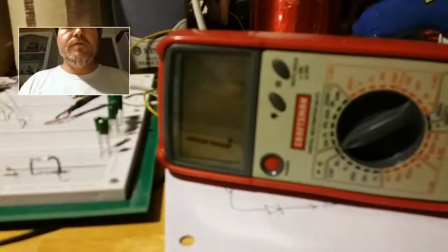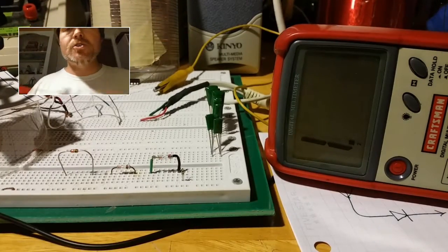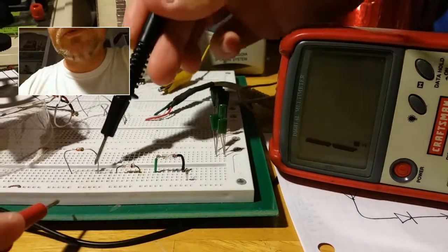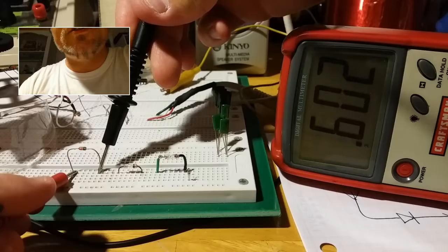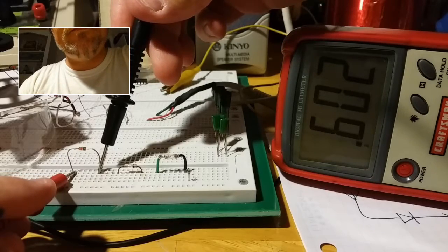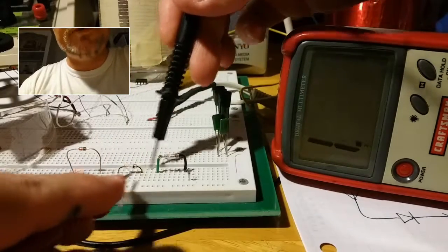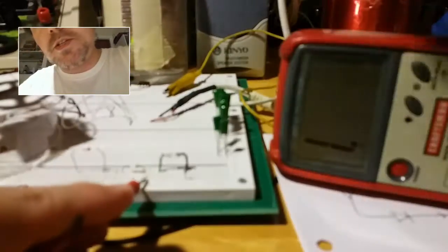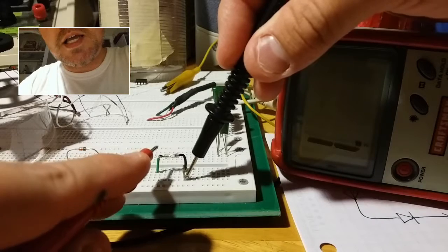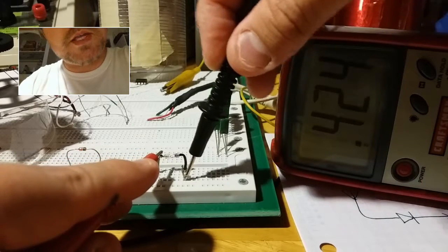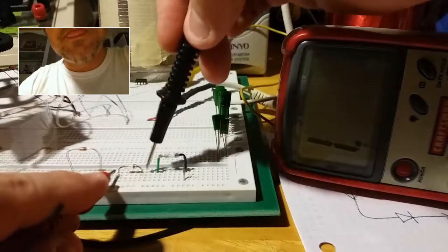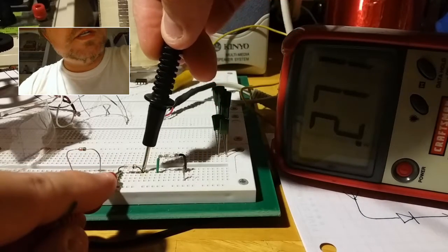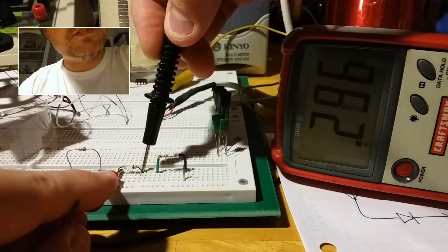Now, if I measure the original diode that I was using in my crystal radio, you'll see I've got a 0.6 volt diode. Well, keep this in mind, but we've got a much better diode to be using. This one here used to be my father's diode. I claimed it. It's older than I am, so I don't like using it, but you can see it's 0.426 forward volts. But this one here is 0.276 forward volts.